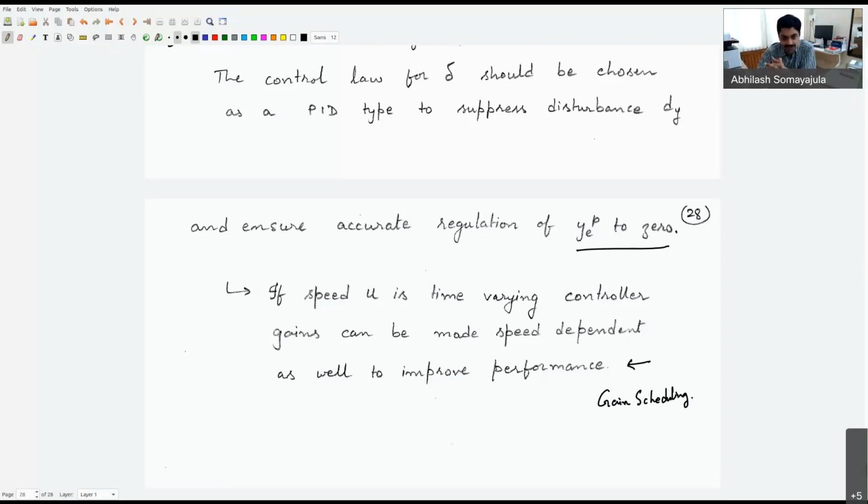So today's idea was primarily about guidance and how that guidance can be used. Okay, so today we have looked at the idea of how we can relate the course angle which we get to the cross-track error, which will help us now to relate our cross-track error to the rudder angle, and then we can use the dynamics there in order to tune a PID controller to drive our plant to execute the dynamics which we wanted to execute.